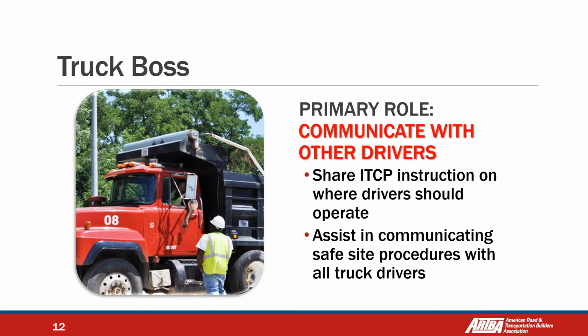Then the truck boss. You have trucks arriving to the work zone constantly. There is a truck boss, so the primary role of this person is to communicate with other drivers. Okay, if there is any change in the internal traffic control plan, that could be our main point of contact. Share internal traffic control plan instructions on where drivers should operate. Okay, what areas are only for traffic, what areas are designated for truck lanes or truck queues. Assist in communicating safe site procedures with all truck drivers.